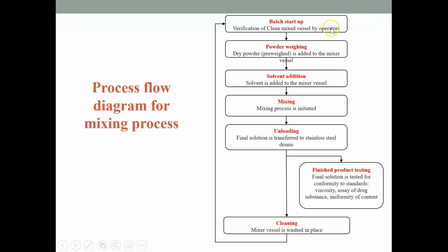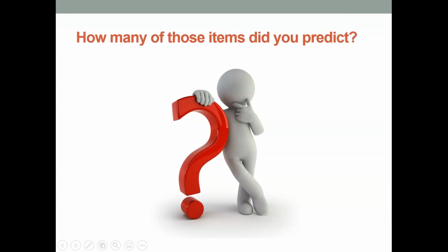So this was our process. We started with our batch, our powder weighing, our addition of a solvent, our mixing, our unloading, finished product testing, and then our cleaning, washing in place. I hope you were able to predict some of these checks.